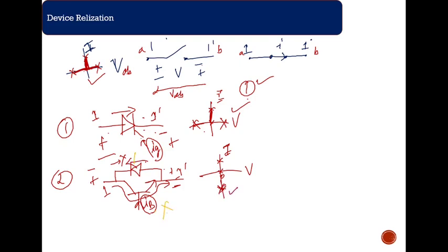Here I can achieve this point. If I remove the bias current and apply plus and minus here, then current cannot flow in this manner, not through the device. So I have achieved the plus minus here. If I apply minus and plus here, then current can flow through the diode here, which is the negative direction. So I cannot match this option to this option. So only the first option matches.